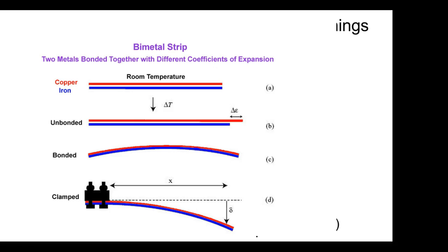So basically, a lot of your home circuit breakers work off this concept where they actually pass the current through the strip. And of course, metals have resistance. There's no such thing as a metal that has no resistance, right? You understand that? So if we push current through resistance, then what does it do? It drops the voltage, but that's not what I'm looking for. What does it do? Because what are we talking about? We're talking about temperature. So if I pass current through a metal, what does it do? It heats it up, right? You understand that? That's why conductors get hot, especially if you use the wrong gauge.